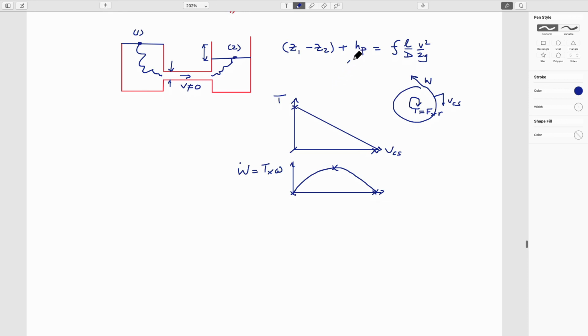So you didn't want me to write Bernoulli, but I will write that the work divided by density, flow rate, and gravity is equal to the head, right? The pump head. And so we could rewrite that as the work is equal to the volumetric flow rate, mass flow rate, I guess, right? This would be, not divided by, but this would be m dot times g, and multiplied by hb, pump head.